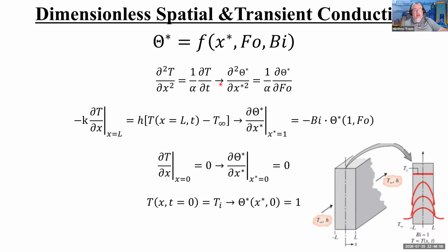Okay, so I've now converted the foundational equation, right? This is F. I now have to solve this. And so I have to also convert my boundary conditions, right? So that initial boundary condition that was the convection boundary condition, right? So the conduction into this outer surface has to equal the convection out of this surface. That's this boundary condition. So I'm just going to go through and non-dimensionalize that, right, the way that I did up here, just replacing the dimensional terms with the dimensionless terms.